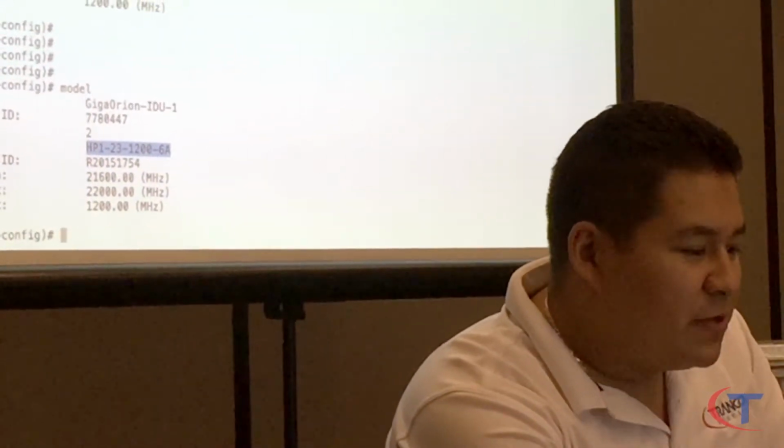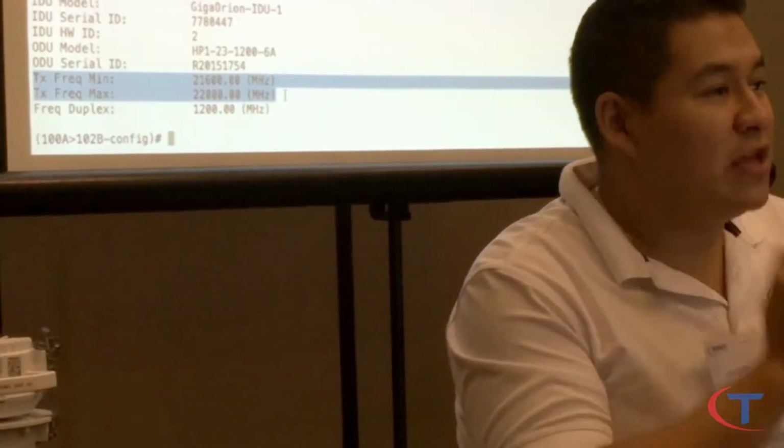Okay. Now something to note here as well, transmit min and max frequency. So I can only set frequencies within that range. If I try to put something outside the range, it's going to say ODU timeout, because it's not in the range that it could be set. So that's actually telling me what that A range is. That is the lower bound. The B is the high side. If I can't remember, I could power that one. There you go. Just the model command.